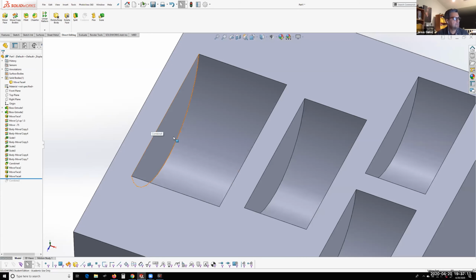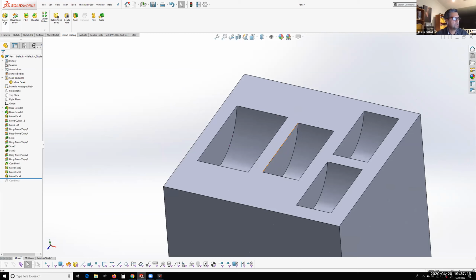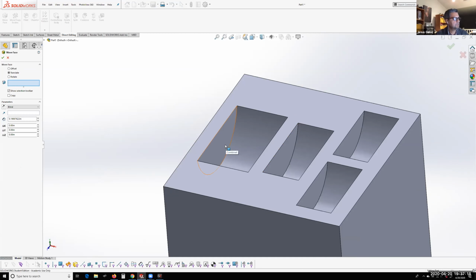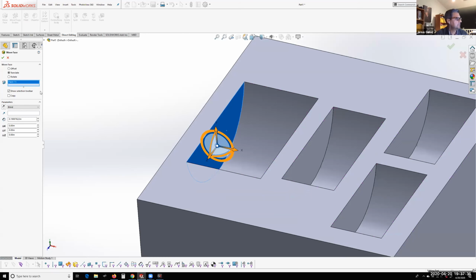That's another simple thing you can do with move face. Instead of having to figure out some complex cut, it might be a complex revolve, because it's not going to be a straightforward cut, as this will have to have some kind of weird draft angle. It might not even be possible with just cut. Probably have to revolve it. But you just do a quick rotate.